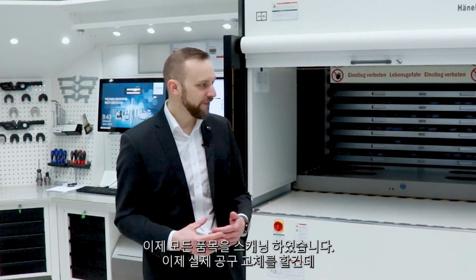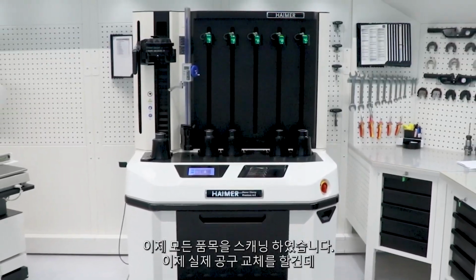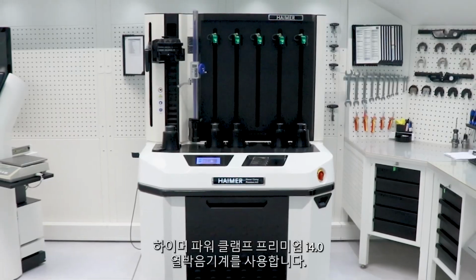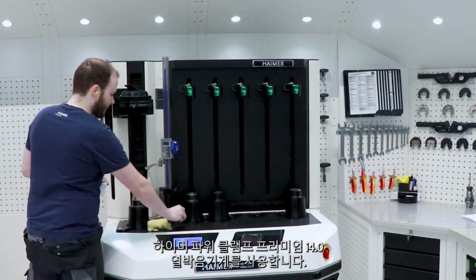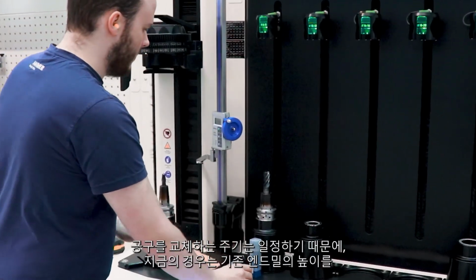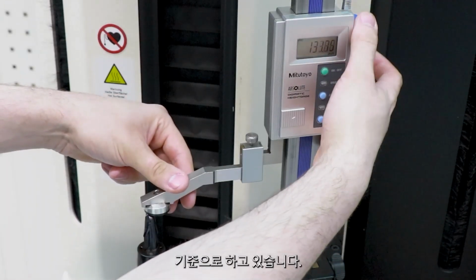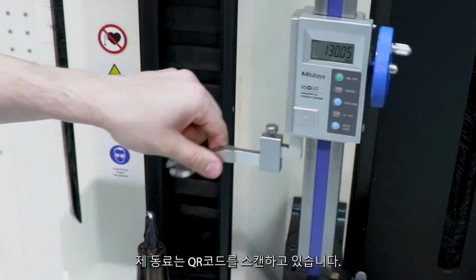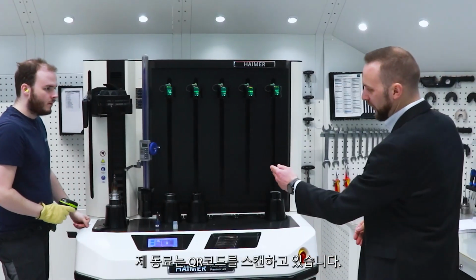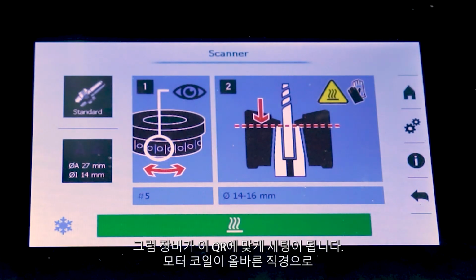But now we're done with all the scanning. Now the real tool changing will start, and therefore we are using our PowerClamp Premium i4.0 shrinking machine. And as there is this constant cycle of changing tools, we are in this case taking the height of the old end mill. Now my colleague is also scanning the QR code. Then this QR code is setting up the machine.